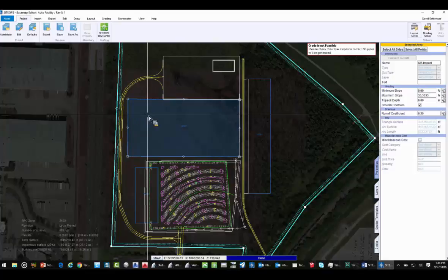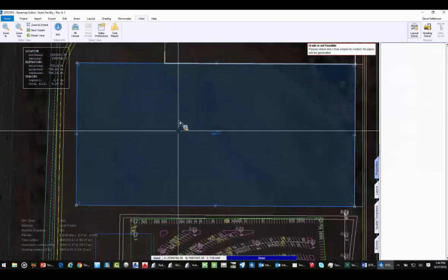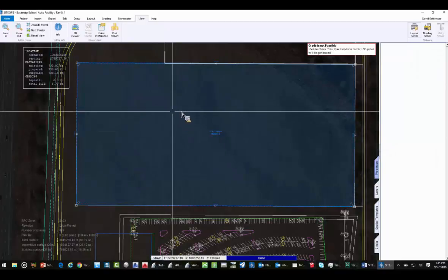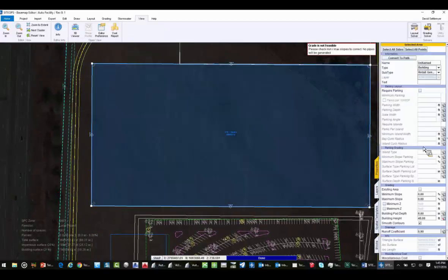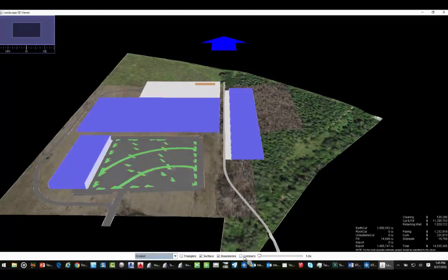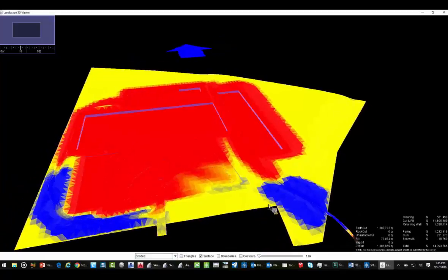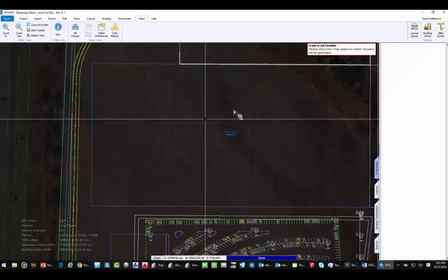So let's see if I can generate something. Let's go in, do a quick info, and see what the existing is on this building. About 732. Let's crank this down to 700 for a maximum elevation. I'm going to try to see if I can generate this problem. All right, I may have gone too far down, but we're going to try. Let it keep going for a minute. We got a lot of cut. Actually, I went too far down. Let's try this one more time.